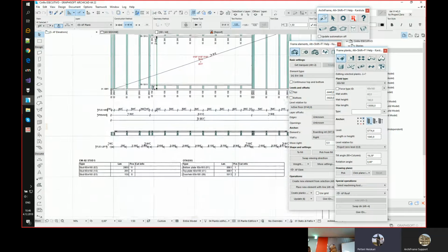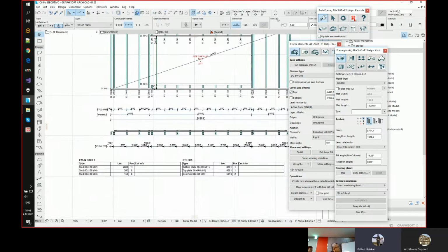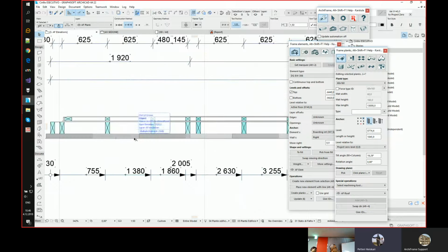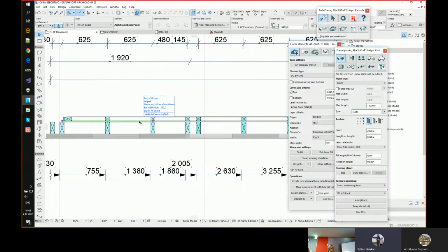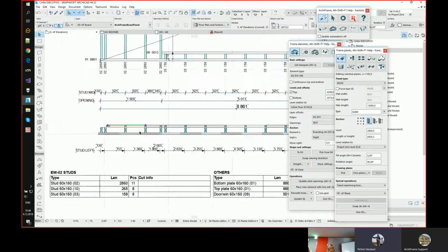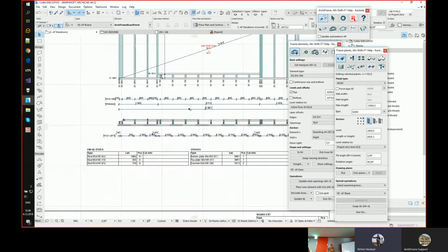Then we have a projection from top, and I'll put the boards visible. So this is everything in the wall structure. So we have insulation boarding. This is the plaster at the exterior side, some OSB here between the framings. And then this is kind of gypsum board at the inner side. Catalyst related to this projection.